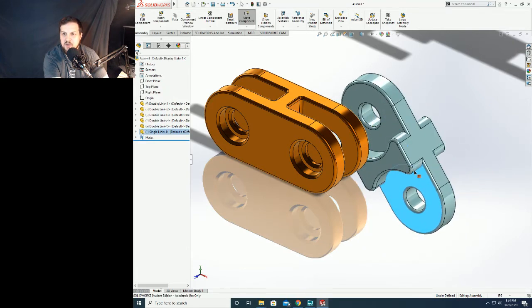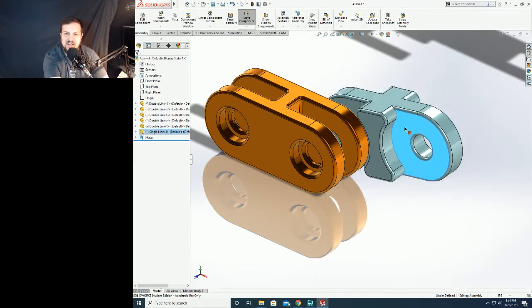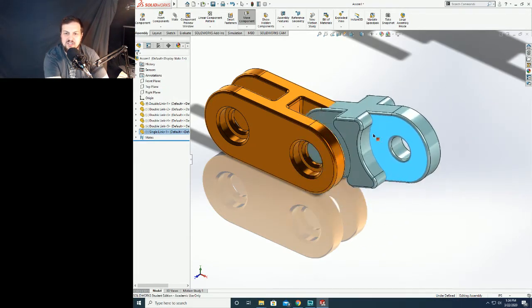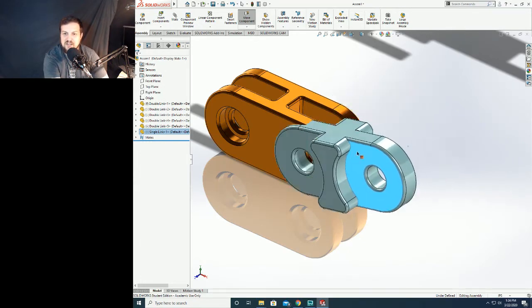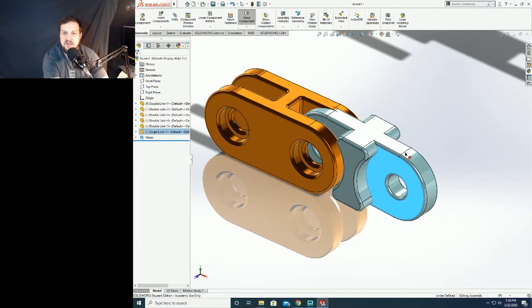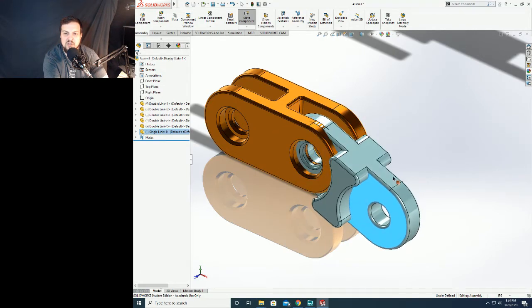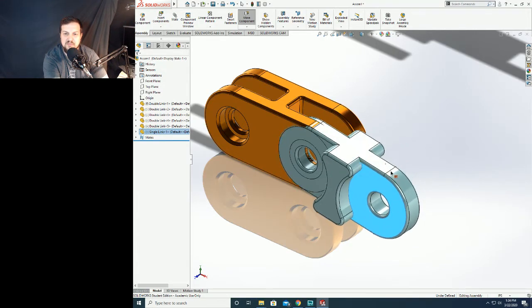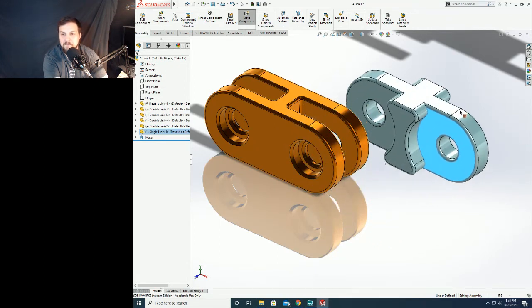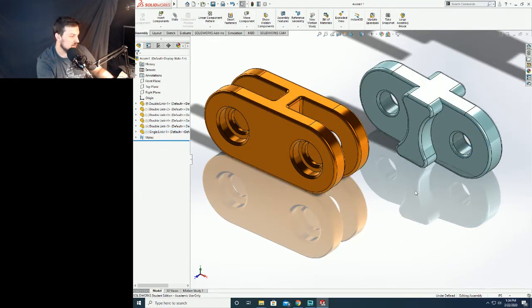As you can see now, those have an actual relationship. So I can still move it around because it's not fully constrained, right? But it also does have a relationship. I can move it around within reason because those are now coincident cylindrical faces. All right? Okay, so I'm going to move this out that way. Now that we've got those cylindrical faces mated, I'm going to...